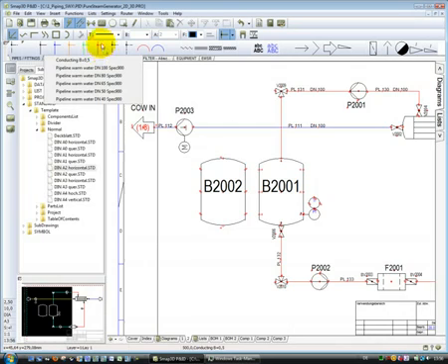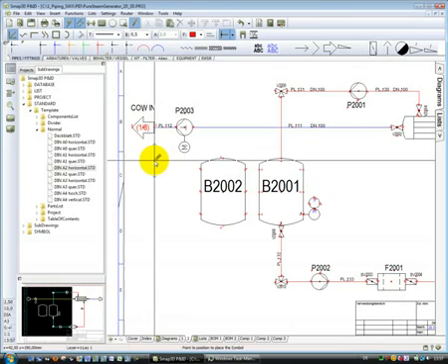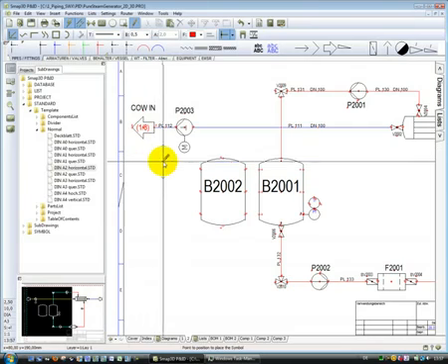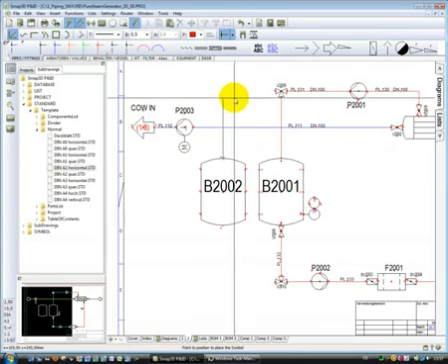If I go to the red pipeline, then such a list appears, and in this list I have access to the associated data sets which were prepared for my red pipeline. And so if I select one of these entries, in my case I need a pipeline warm water diameter 80 with spec 900, and with this selection I have direct access to create a pipeline by clicking here.